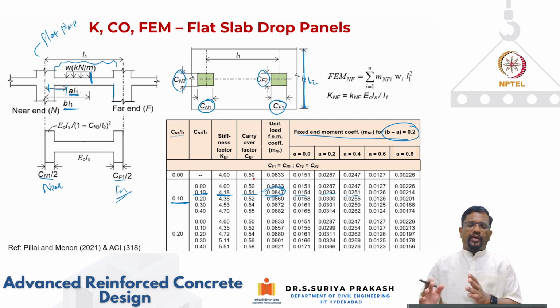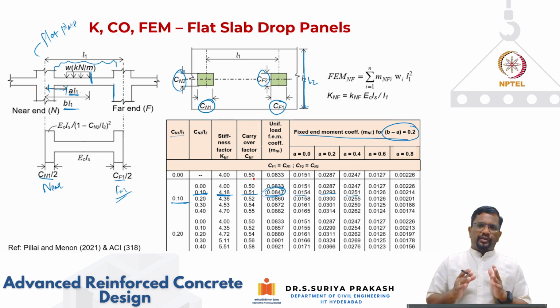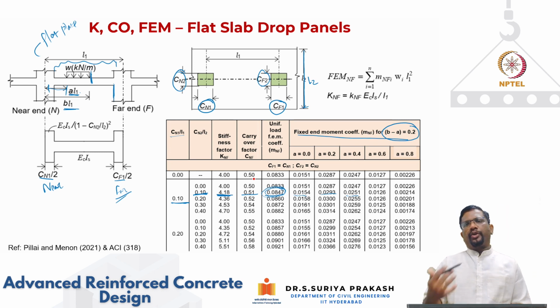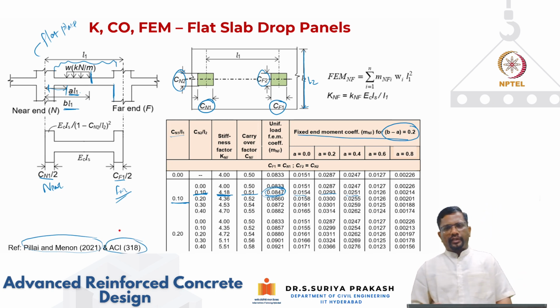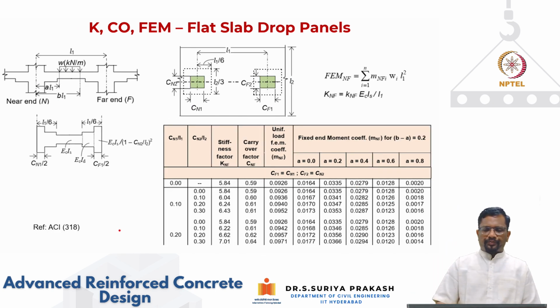So like that we have to do for all the spans. Once your stiffness parameters and loading parameters are fixed, then it is a routine process of carrying out moment distribution only. These tables have been taken from Pillai and Menon, Reinforced Concrete Design. In fact, these were recreated from the values that are given in ACI standard 318.